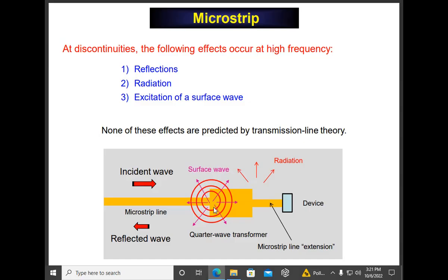And of course, a microwave engineer would never really make a transformer by actually having an iron core with a primary and secondary winding. That's what power people and electronics people do. Remember, in the microwave engineering world, we like everything to be planar, like for example, with microstrip technology. So we can get any impedance we want, like with short stubs, we can get transformers, right? Everything can be done with microstrip. That's the way microwave engineers like to work. Okay. Any questions on that?